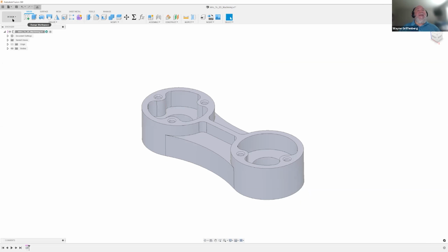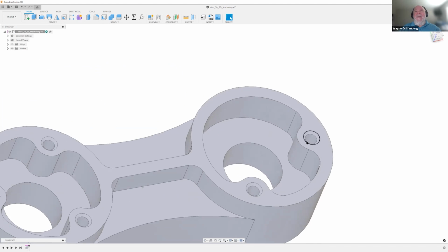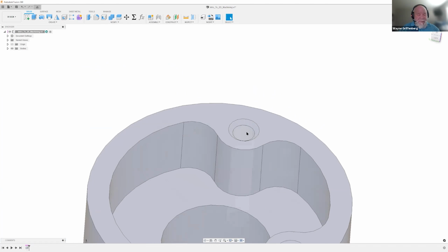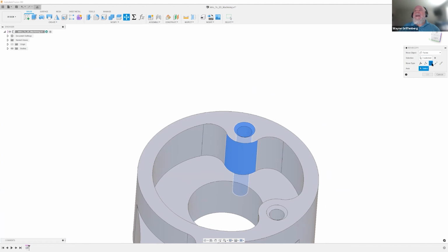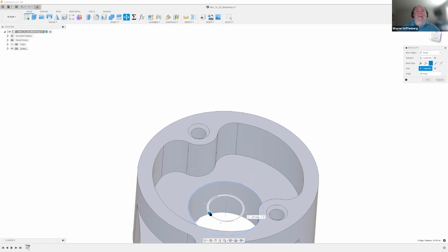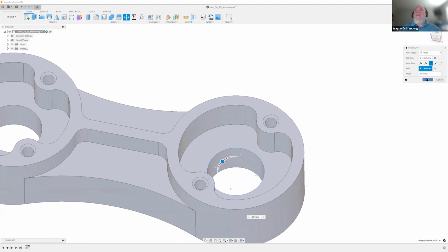So I just simply jump back to the design, and the customer wants, like, we remove that one hole, but they want to rotate this hole around, right? So we want it to be opposite on the other side. I'm just going to grab that geometry. I'm just going to move it. Just choose move. I could select this center point of this axis, and I can rotate that hole right around to the other side of the part. So maybe I'll go 66 degrees or something like that. There's 60 degrees.